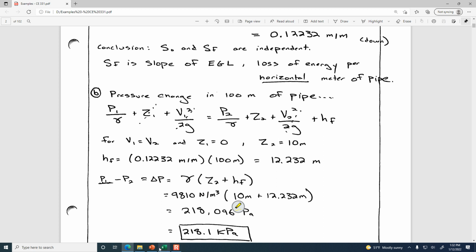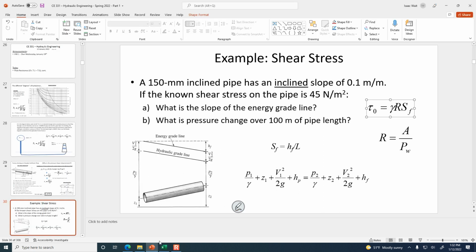So think about location 2. Even before you started doing the calculations, would you expect that the pressure down here at location 2 is higher pressure or lower pressure? Well, both of the things causing a change in pressure operate in the same direction, because the hydrostatic effect is saying the pressure is going to be less at 2 because it's higher up in the fluid. Remember, as we go down through the fluid, the pressure is higher. As we go up through the fluid, the pressure is less. So that's part of it.